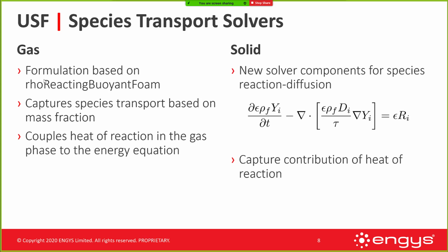For the solids, however, we needed to add something new, which was a solver to capture the species reaction diffusion physics inside of the solid itself. Something that's, I would say, a little unique is that the porosity of the solid is captured. We have the mass fraction of each one of the species, but then we also have the tortuosity of the solid structure itself. So coupled with the porosity and tortuosity, we're actually able to capture some of the complex structure of the porous media itself, more so than we would with another model.